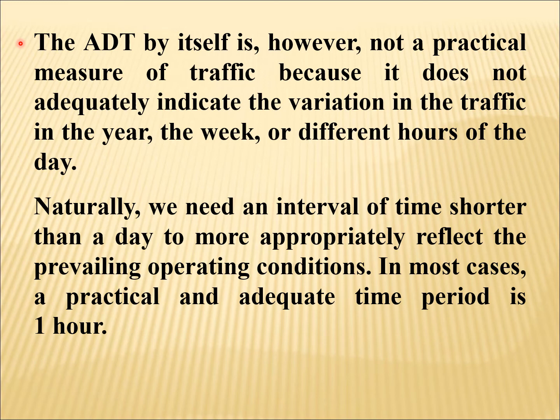The ADT by itself is, however, not a practical measure of traffic because it does not adequately indicate the variation in the traffic in the year, the week, or different hours of the day. Naturally, we need an interval of time shorter than a day to more appropriately reflect the prevailing operating conditions. In most cases, a practical and adequate time period is 1 hour.